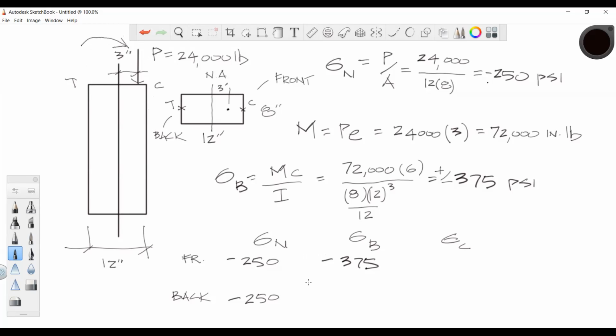It's kind of like to look at the shape more like malleable rather than like fixed. Yeah, you can think of that, but what you really need to remember is that stress is not a force, number one. It's what's developing within the material so that it resists that force, right? So the force, you can look at it this way too. The force here would be a tension force, and the force here would be a compressive force.